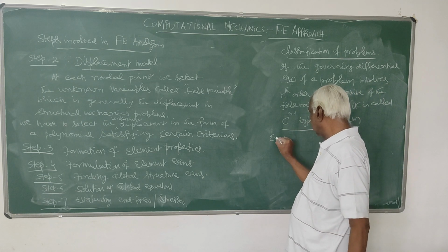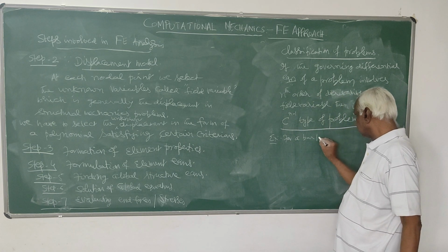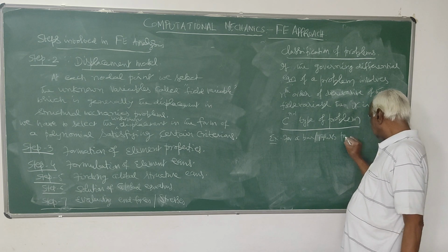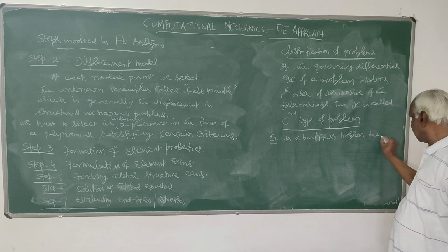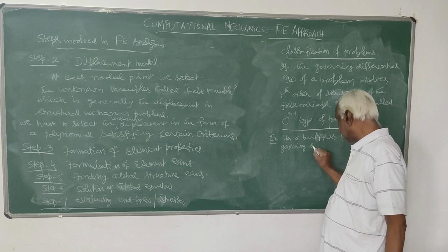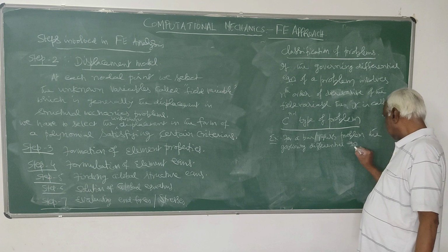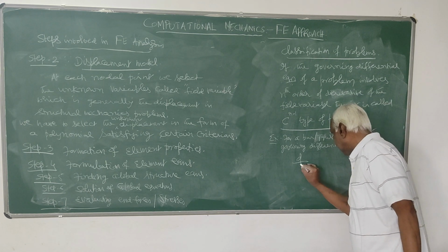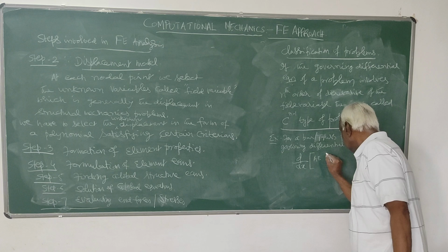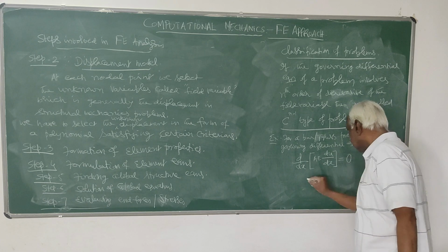So for example, for a bar problem, the governing differential equation is d by dx of AE du by dx is equal to 0.